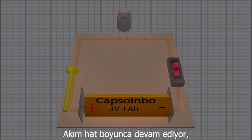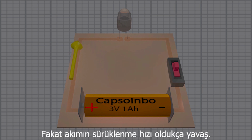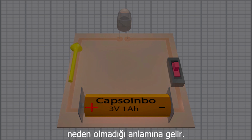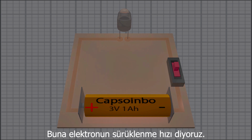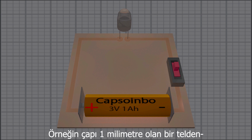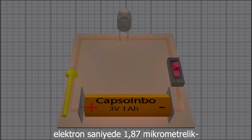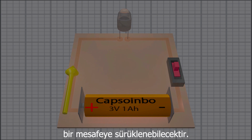The current is moving along the line, but the drift speed of the current is very slow. This means that the flow of current does not cause the LED to emit light. We call this the drift speed of the electron. For example, if a current of 20 milliamps was passing through a wire with a diameter of 1 millimeter, the electron would be able to drift a distance of 1.87 micrometers per second.